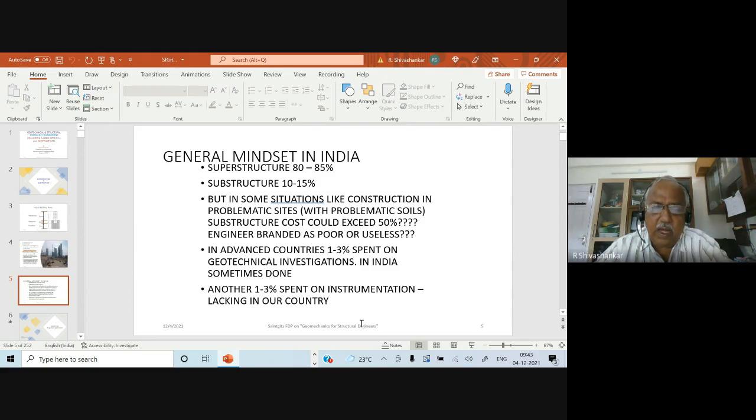And you can take actual measurements of the structure, and you can compare this with your design. In your design, you would have predicted some settlements, predicted some base pressures. So you can compare your design with the actual data obtained. So that helps us or gives us more confidence in our design. Sometimes what we predict is far away from the reality.